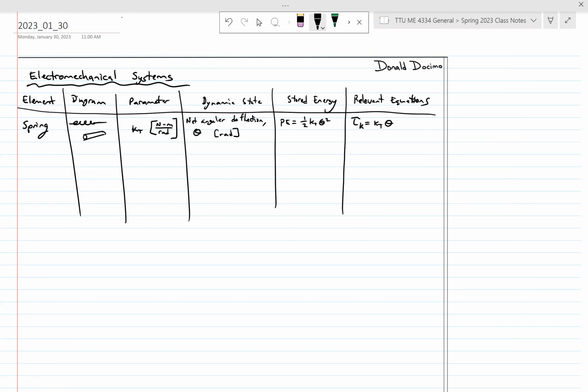If you want to convert it to a force, you could. But we're going to, with rotational systems, deal with our torques. The other equation, right? It's the rate of change of our deflection would be the sum of the angular velocities of each end, right? Or omega net, right? That's our spring. So that's our first element, first passive element.